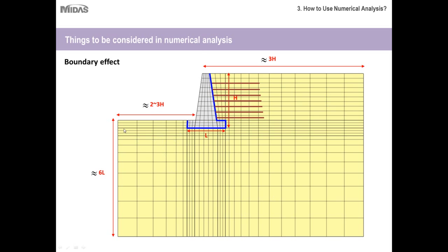When you are looking at the results, if you see the stresses are not zero at these ends, but rather they have some significant value, and you can see through contour plots, you would have to take a bigger boundary until you reach a point where you don't have any more stresses at the outermost boundaries of the soil strata.